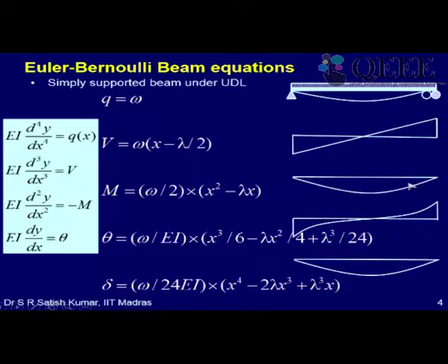So here we find that at the ends the bending moments are low, so the curvatures or the slopes would be fairly small, and then as we proceed, the slope should be very high, and then it will reduce to 0. Okay, so here it is very high, it comes down, but notice that this is going in a concave fashion, not in a convex fashion. So you have to understand that also. So it goes like this because the slope of this is my theta.